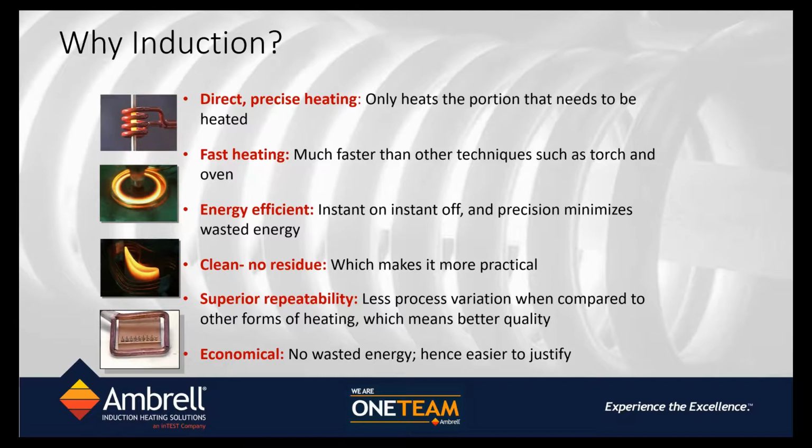And because we are traditionally heating just a section of the part, or just affecting a small portion of the part, the amount of energy that is used with induction is much lower. This not only leads to quick heat up of the part, but also quick cool downs of the part, contributing to this entire efficiency debate.